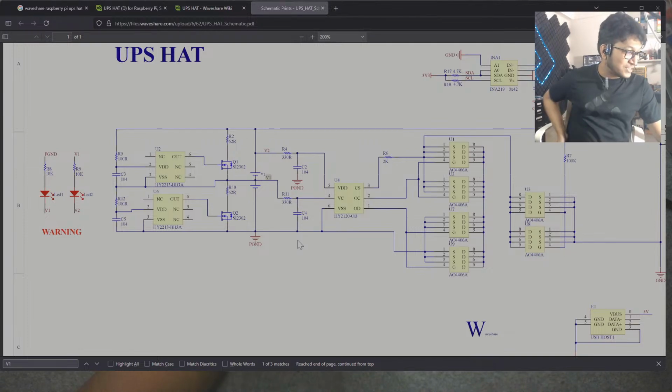That's also 2S, because it's that much easier to take any kind of voltage like 12 volt, and take it down to 8.4 volt, and then from there the lowest voltage you can reach from 2S is 6 volt, because 3 volt each battery. And so as long as the output voltage is 5 volt, you can just work with a buck converter. There's no buck boost required. So this is good. Okay, that makes sense.